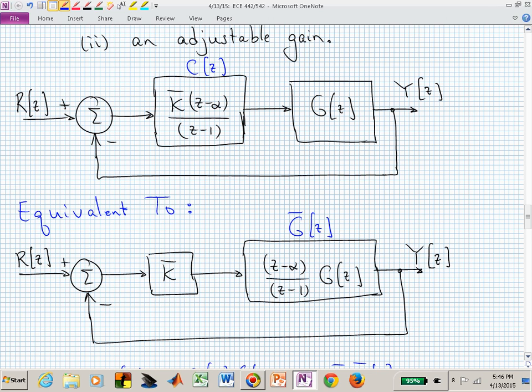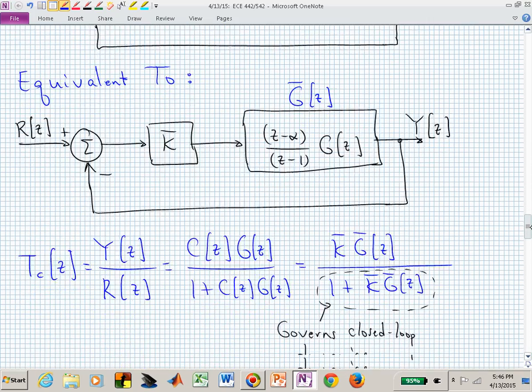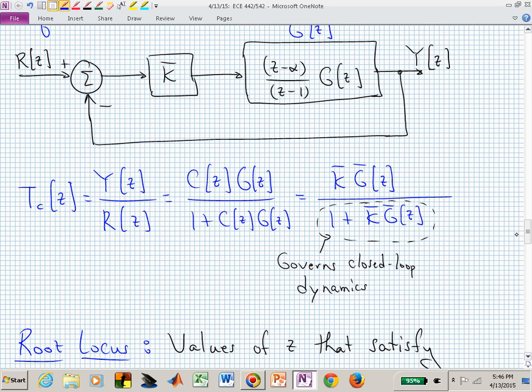And I could now place my closed loop poles in the appropriate location to achieve the transient that I want. And if it's with a PI, you maybe already have the steady state accuracy that you were looking for. Again, that K bar allows you to manipulate the closed loop poles, but you don't have total freedom over those closed loop poles.